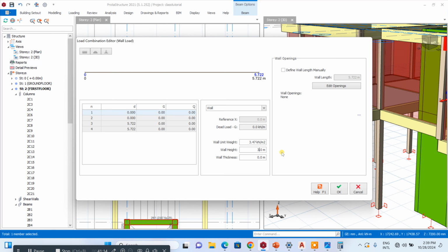Okay, so this is our ground floor, this is our first floor, this is the second floor. So we're going to our roof now. You can see that we have actually done what we normally call in our AutoCAD general arrangement here, but we just imported our DXF file, and from there we are able to insert our columns and our beam. So whichever way is simpler for you, you can decide to use it.